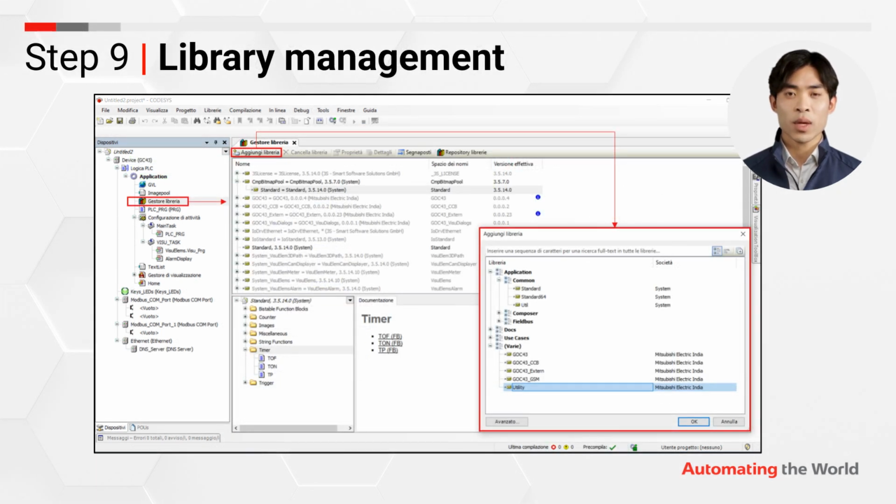Step 9. Library Manager. We should remember that, in the Codesys environment, there are preloaded libraries ready to use once activated. To add libraries, check compatibility with the version of the development environment in question.